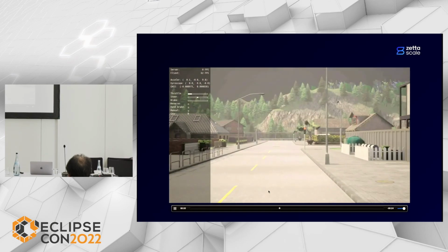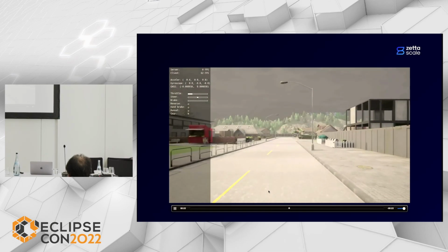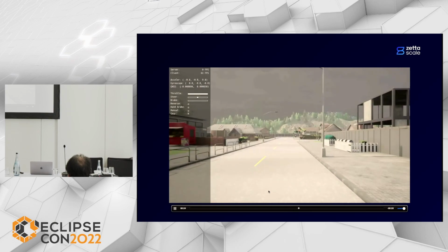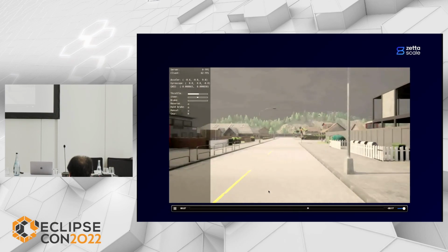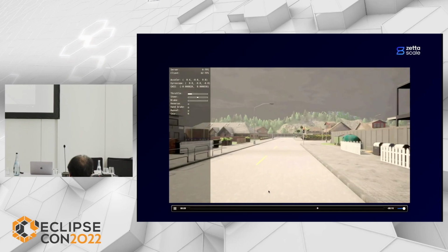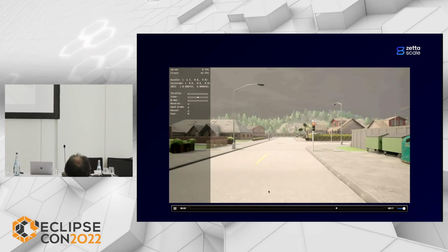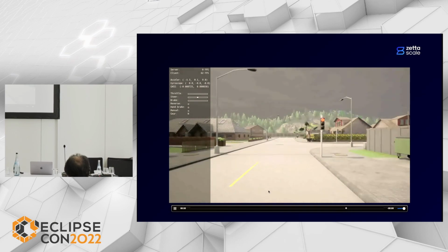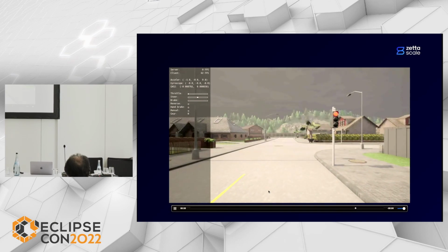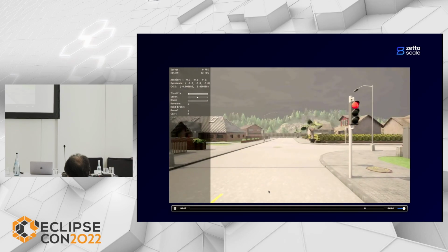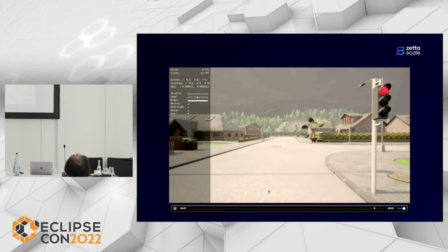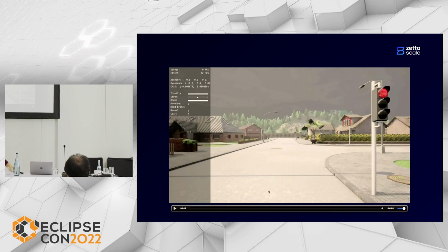This is done using the perfect perception, so we see that the car is able to drive in real time. If we change this pipeline to use the AI, it will be way slower, just because Pylot per se is written in Python, which is not perfect for performance, and it also uses different kinds of AIs for all the detection, plus the LiDAR and so on. So this will slow down the whole simulation. There is also a problem that comes from this simulator: as you start adding more and more sensors, each sensor will slow down the simulation itself.